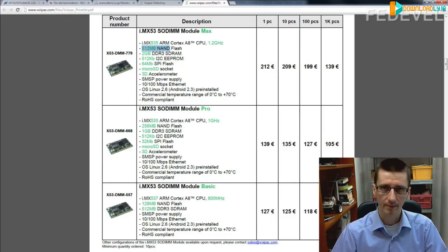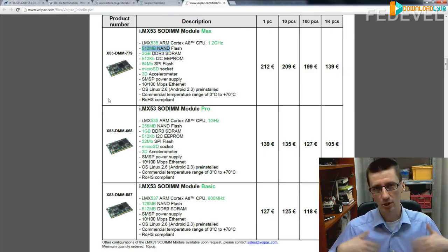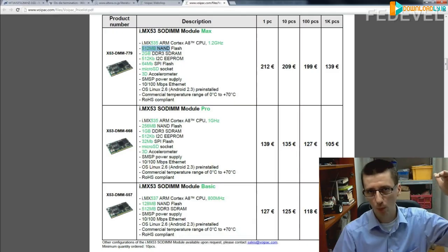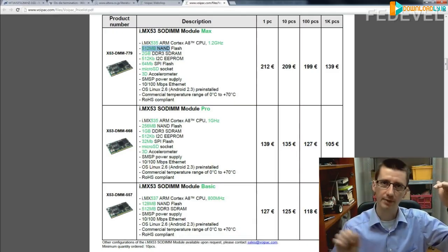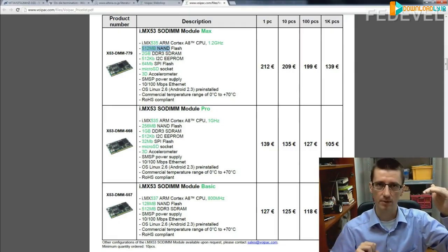What's normally happening, and what I used to do before, is I created the schematic, the board, and then I generated the BOM from this schematic and I manually created all these 3 variants. So I went through the full BOM and I removed the unfitted components, or I replaced, for example, the processor with different processors.